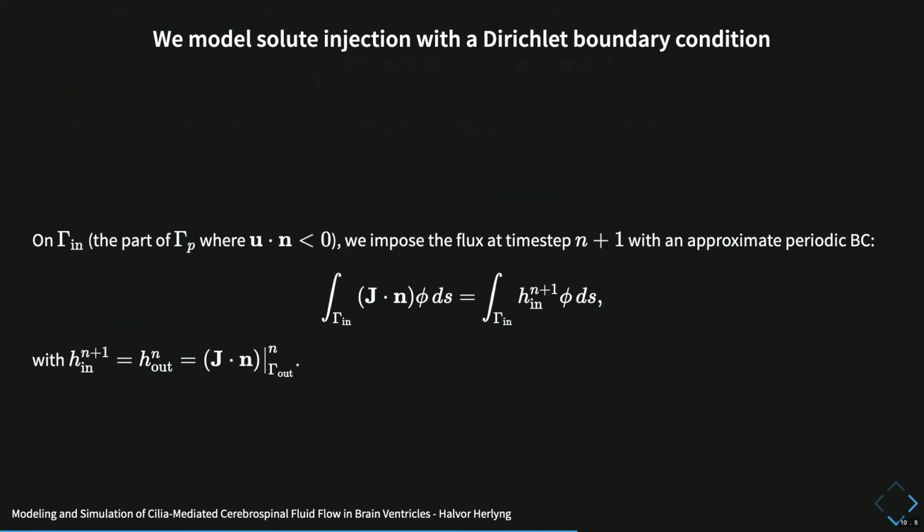And on the part where the fluid is flowing in, we have an approximate periodic boundary condition where we just say that what's flowing in is what flowed out at the previous time step, in the lack of a better approach.